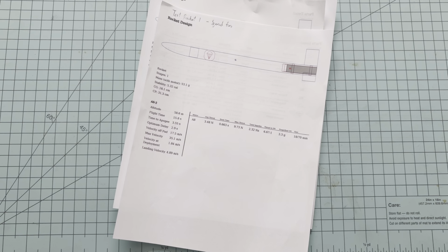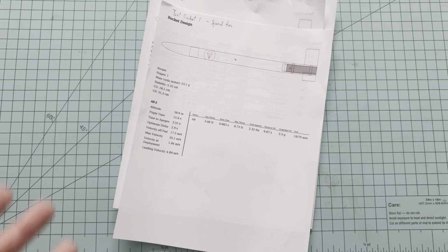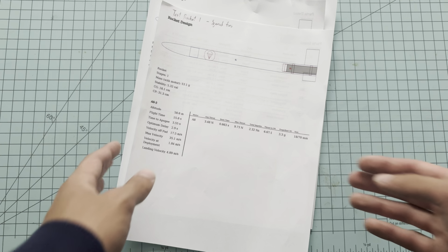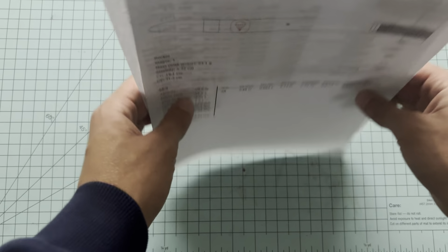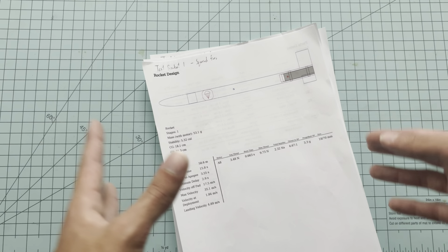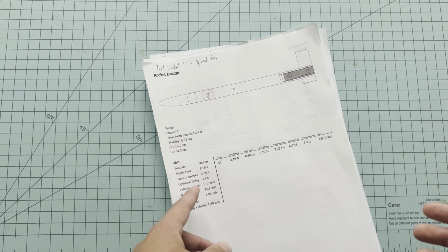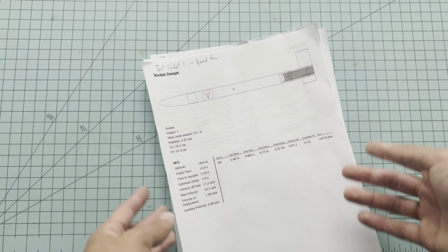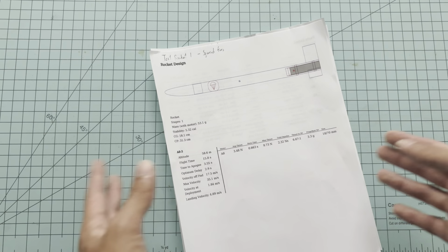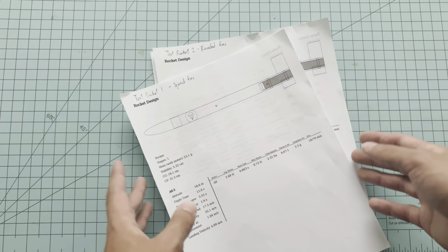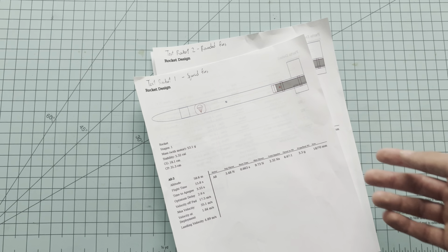The good news about model rocketry is that we have OpenRocket, which, if you're unfamiliar with it, is really awesome. It's a free, easy to use software that really does everything as far as designing model rockets goes. You can put out your components, and then it has the motors. It'll give you predicted data on how high the rocket will go based on the details you gave it and the motor that you chose. It'll also, most importantly, show you the stability, a simple gauge of it: the center of gravity and the center of pressure.